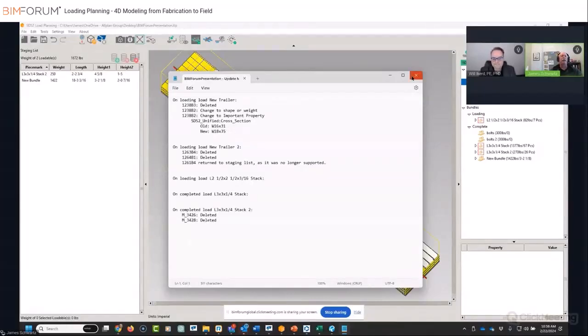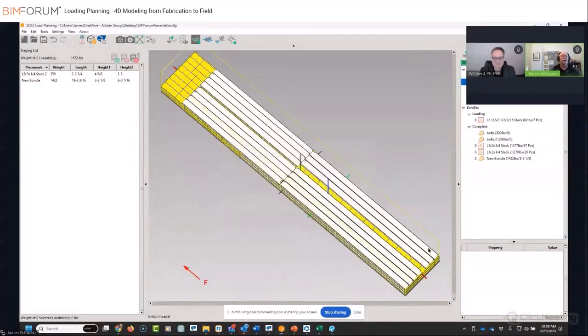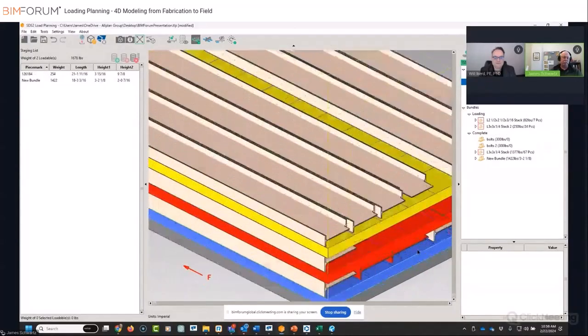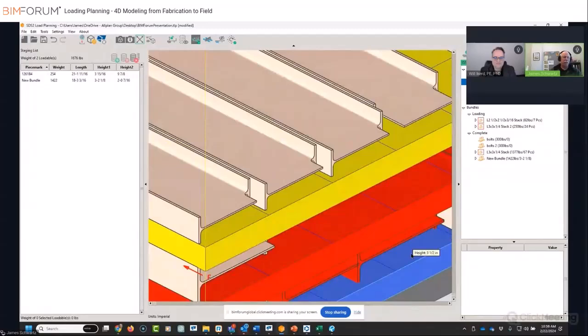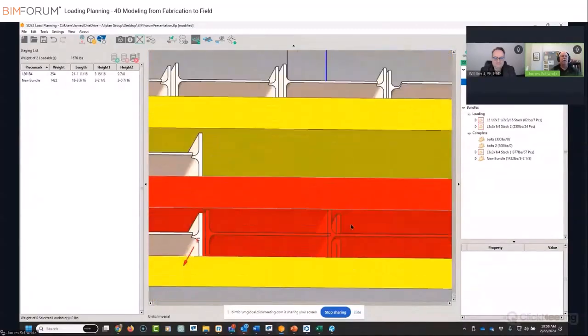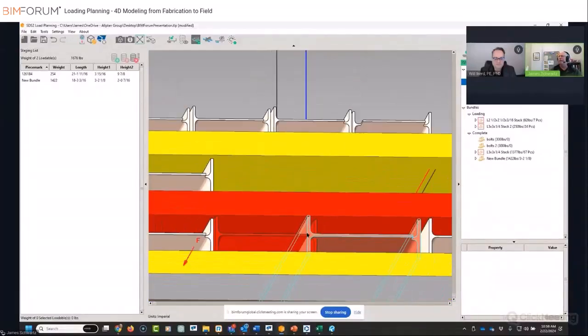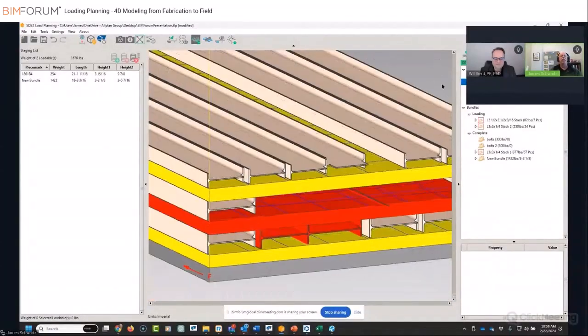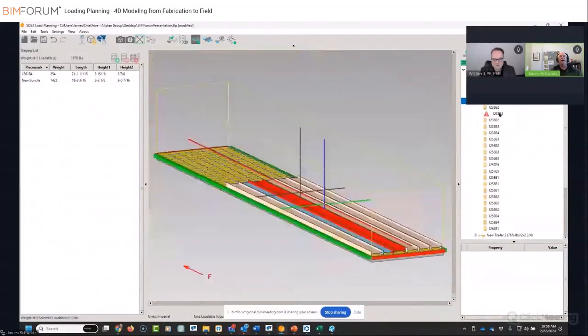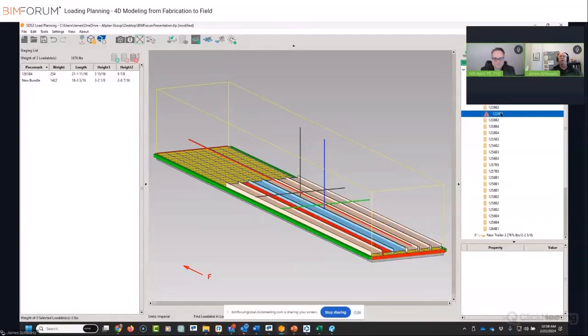And that's what happened right here, I ran through this thing. I'm an audit trail person. Give me that document telling me that this is exactly what happened. And you can see right here how these now are hitting each other on this particular trailer. See that? So it gives me that information, and I love that feedback, because those beam sizes adjusted. So you can see how you've got this ability to go through, and it turns it red and puts this information on it, which allows me to go and find out exactly what's going on.